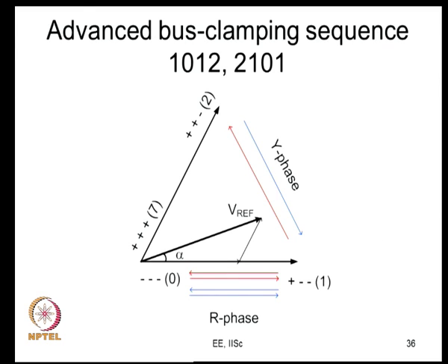Now, there are variations. This is where space vector based PWM is a little different. You can apply one of the active vectors twice. We saw an example earlier where you can apply 0 and go to 1, do not stay for t1 seconds, stay only for t1 by 2. Go here, stay for t2 seconds and come back here and finally spend t1 by 2 seconds, that is 0, 1, 2, 1. We saw this example when we did the space vector based PWM module, and also when we did the analysis of line current ripple. Now, there is another variation we are just looking at here.